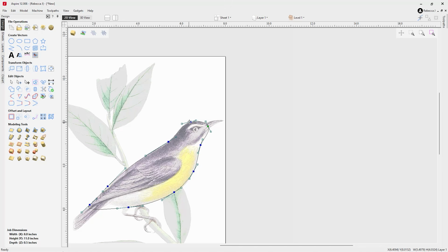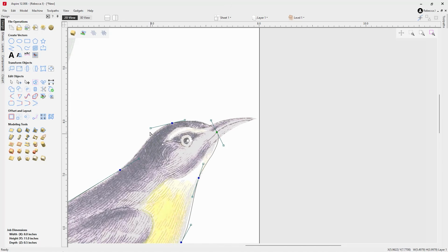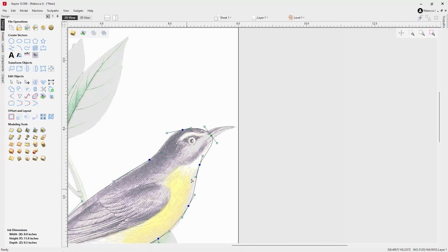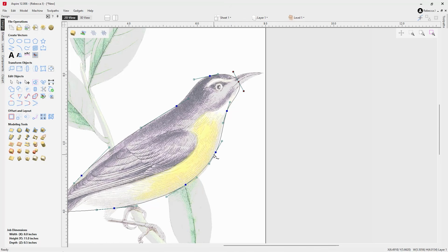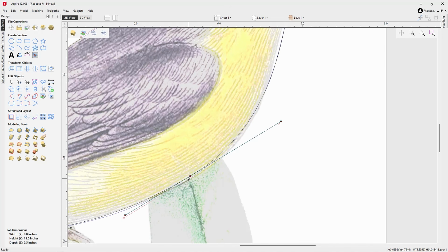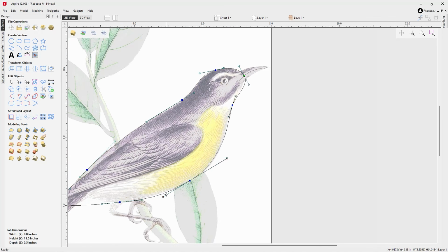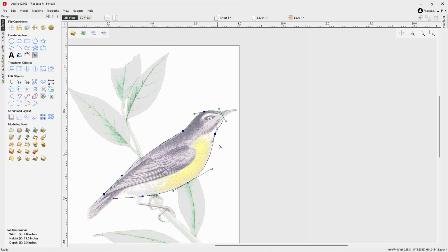to really control the overall shape of the part that I want. Now, the best results that you're going to get with creating 3D models is by having vectors that have minimal points. So you don't want lots and lots of dots here. You want nice long smooth curves, especially with natural forms. Then over here I could delete this point by right clicking and deleting it, and then I can pull on this handle to give me a nice elongated curve. Pull on this handle too to really control the curve, maybe bring it down a little bit, and then nudge that handle up, and you can see I've got a really nice smooth shape.